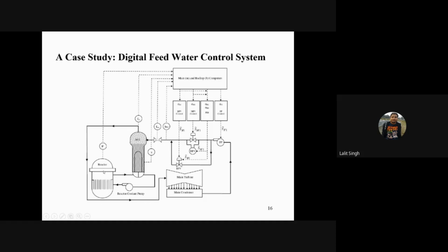So what happens here, a lot of heat energy is there, and so there is a reactor coolant pump which is pumping the cool water in a pipe. This arrow is nothing but a pipe, and it is going from inside the reactor. Then definitely the heat will be transferred, and you can see an elliptical dome shaped structure on the top. This is known as a steam generator.